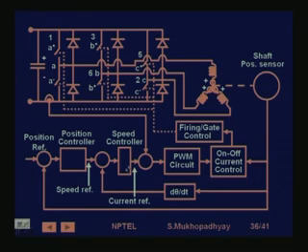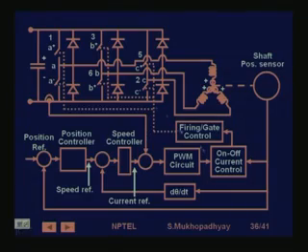Now the speed reference is compared with the speed feedback, and we have seen that the speed feedback actually adds damping and gives very good motion characteristics. Then the speed controller will generate a current reference. Now the current reference is similar to the torque reference because the flux is constant and because it is always maintaining nearly perpendicular, right.